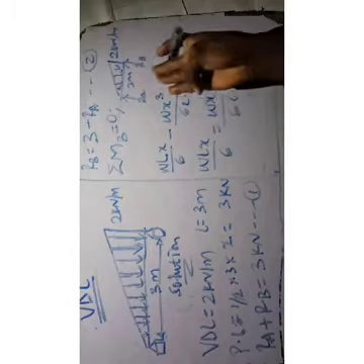Okay, so if what you're looking for is RA, in a nutshell, after you've done this equation here, you can just simply say that RA is what? Remember, RA is WL over 6. Okay, so not to waste time, after getting here, you can decide to put the formula that RA equals WL over 6, or you can just take your moment like I did now.